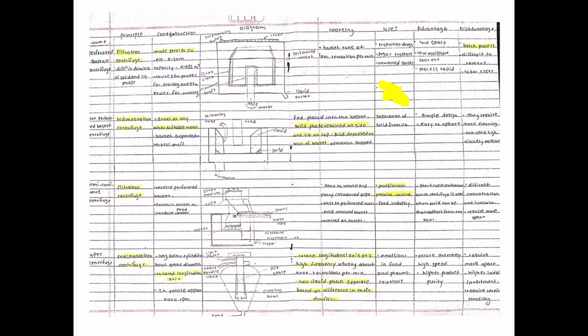During centrifugation, the liquid passes through the perforated wall while the solid phase is retained in the basket, and the liquid leaves the basket and is collected at the outlet. The cake is then dried as much as possible. Sometimes high speeds are used so that the cake will be completely dried. After a definite period of time, the power is turned off and the material is removed. The perforated basket centrifuge is used for separating crystalline drugs such as aspirin from mother liquor, and removing unwanted solids from liquid. Sugar crystals are also separated using it.